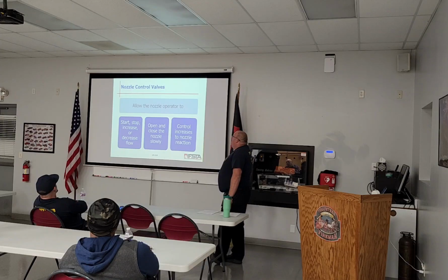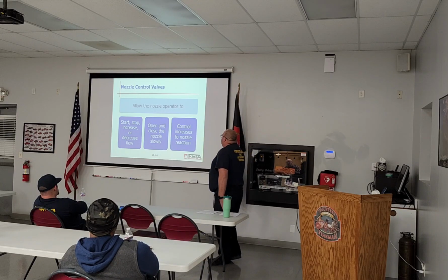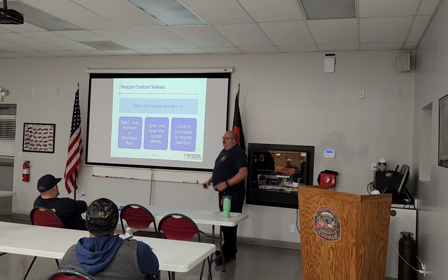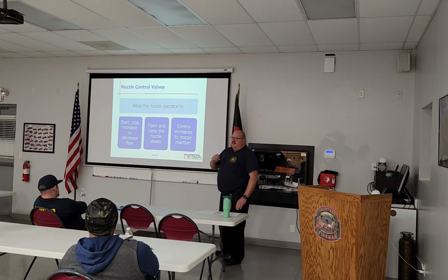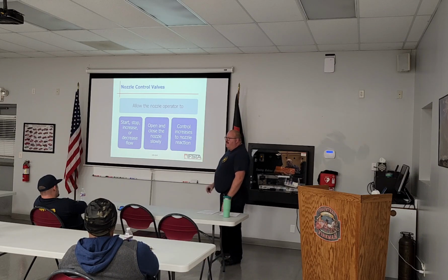Some nozzle control valves allow the nozzle operator to start, stop, increase or decrease the flow, open and close the nozzle slowly, and control increases to nozzle reaction. So your brain's the one operating that nozzle. You know when you want to open it and close it. You just want to make sure that you do it slowly because you don't want to cause that water hammering to the truck or the other firefighters.